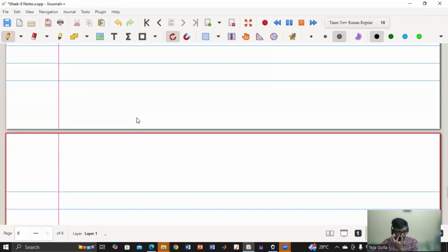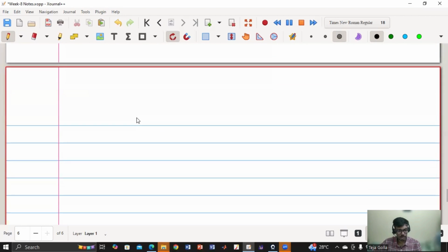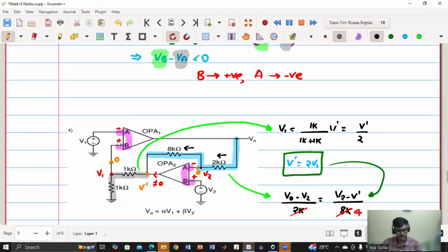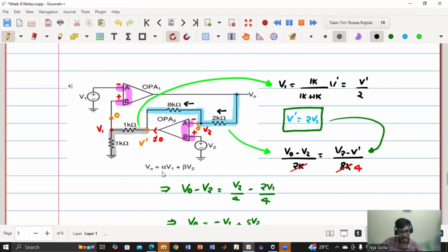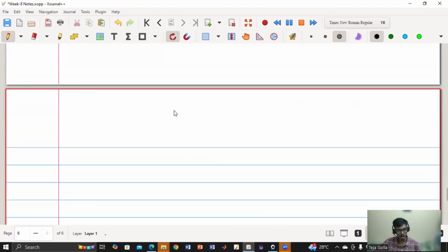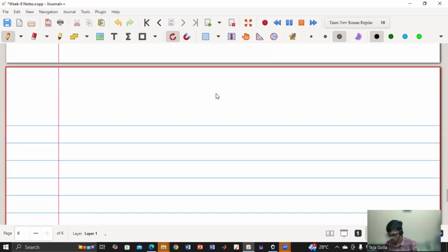But at this time, even if I explain, it will go over your head because you don't have a controls background. So at this point of time, you can assume that negative feedback is needed for stable operation, and in order to make it work like an amplifier, such that we get some gain times the input voltage, it should be connected in negative feedback. Also, if it is connected in positive feedback, the output could be saturated to either plus VDD or minus VDD, which are the supply voltages, which is what we are going to discuss now.